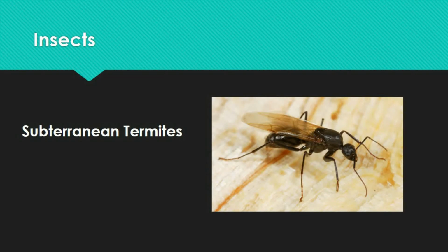Now, the third type of insects that I want to talk about are termites again, and these are called the subterranean termites. These termites are similar to the dampwood termite, although they're a bit smaller, at around 1/4 inch long. The colony prefers to reside under the ground and only attacks poles in search of food. These termites use mud tunnels to go from their nest to a food supply, or a wood pole in this case, which is surely an indication of their existence in the wood pole. So be sure to look for mud tunnels. Termites may be found throughout all of North America.